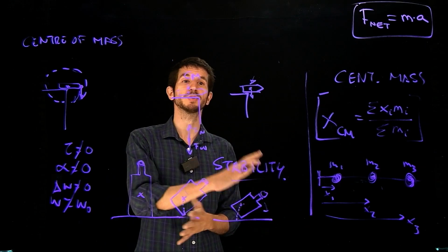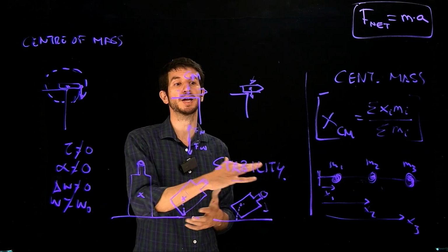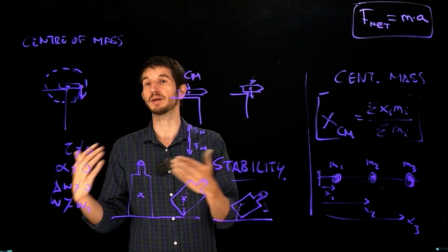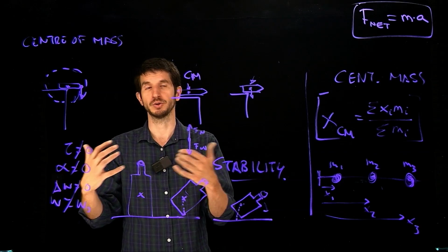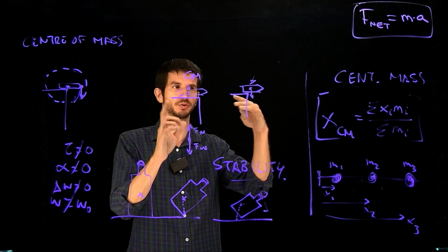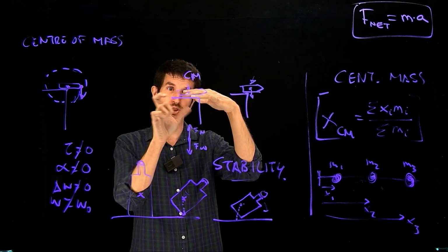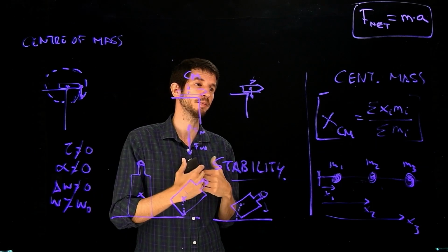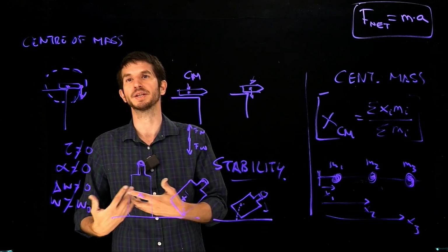And we can also deform the shape, and when we deform the shape, we apply forces that are parallel to the area where we are applying that force. That produces a shear stress, which arises as a result of a shear strain, which is how much we are distorting from the original position divided by the distance, and the proportionality or the elasticity is given by the shear modulus.